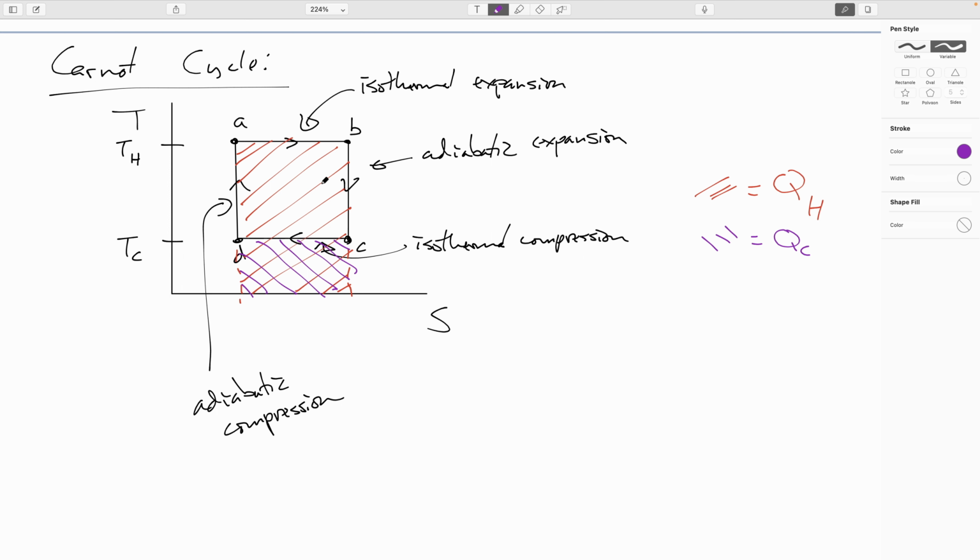So the difference between those two, by the first law of thermodynamics, since we're running a cycle, delta E thermal is 0, means that the work we get out of this is going to be the difference between the Q hot and the Q cold. So this area here that I'm going to cross-hatch in green. There.